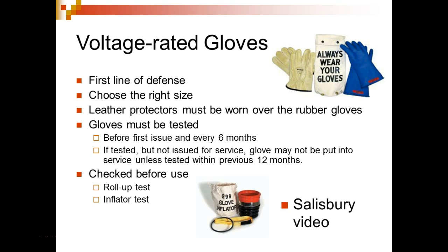Yeah, but see, something's going on. Where was this at? What surprises me is why they didn't have overload protection on it. Well, see, the problem is that an overload protection will start tripping, and if it keeps tripping, which means you're having problems with the motor, they'll go in there and turn the overload up.